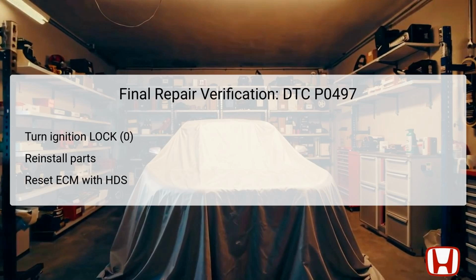Following reinstallation, turn the ignition switch back to the on position. Additionally, reset the Engine Control Module (ECM) using the HDS, which allows it to recalibrate after repairs. Complete the ECM idle learn procedure and finish by performing the EVAP function test again through the HDS. A successful pass of this test confirms that the repairs were effective and resolves the DTC.